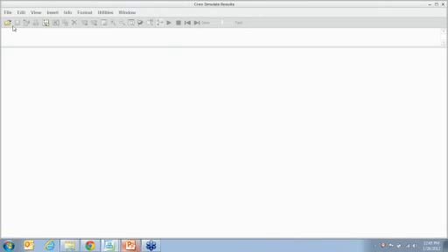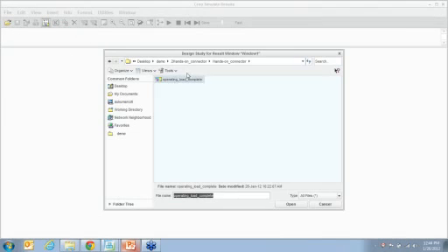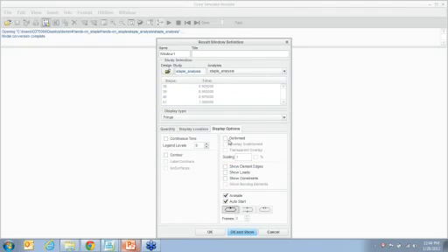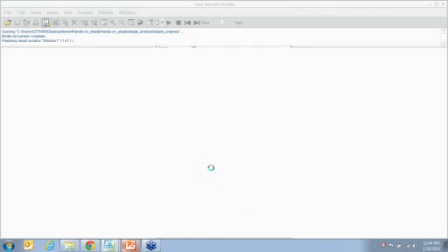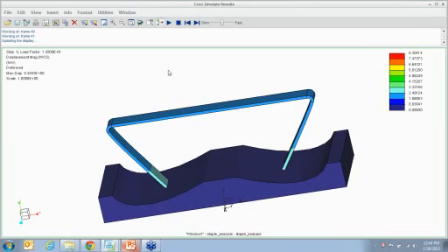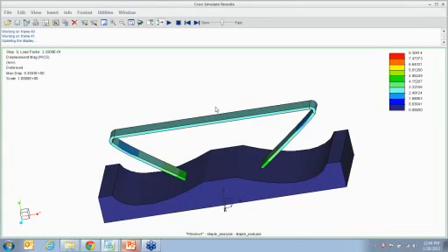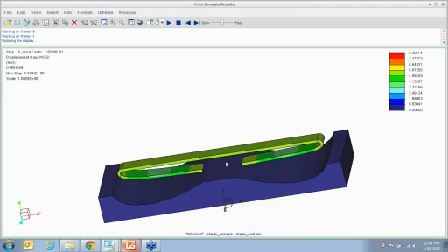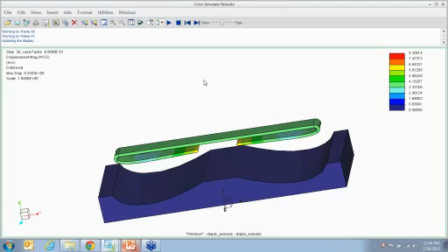So let's look at the result for this. So let's say I want to look at what happens at time 1 second, and I want to animate it and I want to deform it. So we can see as to when the time hits 0.5 seconds, it's going to move to 5.8, and then it's going to go back up.